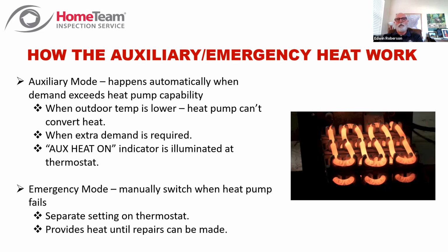In other words, if you've had heat pumps and you live with them, if you ever walk by your thermostat and you see that message aux heat on, well, that means the heat strips are running. And that's one of two reasons. One, it's just so cold outside that the heat pump can't keep up by itself. Or the second is you've told that system you want more heat than it can give in the time. You're looking for a lot of heat right now.